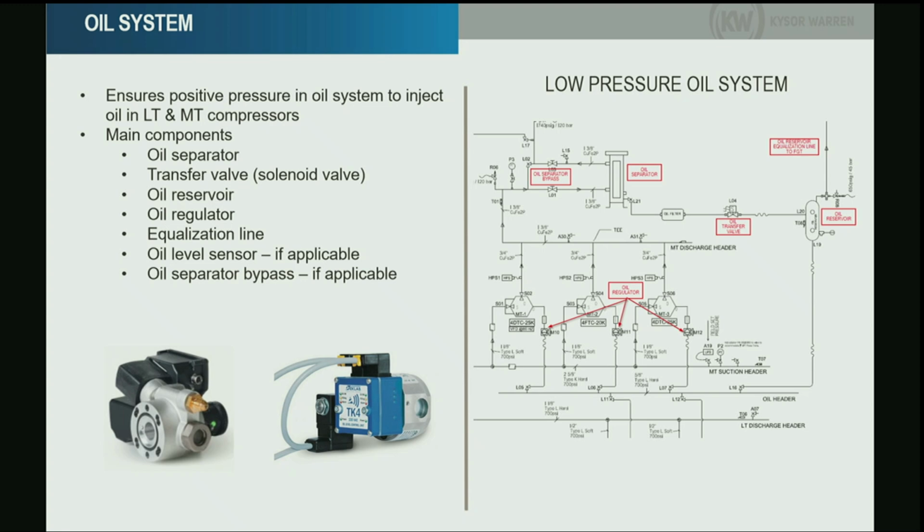Those components here will be the oil regulators that we have installed on the compressors. They are rated for the proper pressures, either operating pressures or pressure differential, that they can manage to inject the oil in the compressors. With those flare connections hold that pressure? Yes. Also, the hoses that we use are rated for 120 bars.